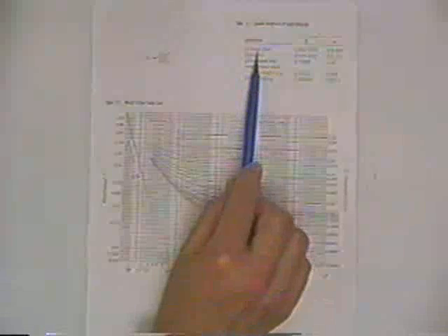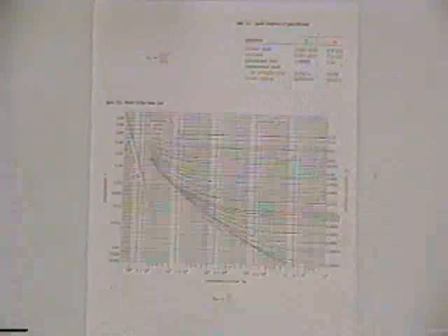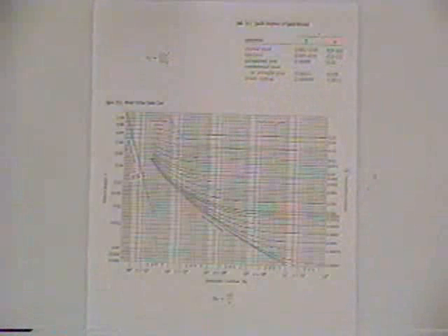And of course, the rougher the pipe, the more head loss you would anticipate. And so in your reference manual, you'll find a very brief table, and other references have very extensive tables that for different types of pipe give you the roughnesses in either meters or in feet. Now if you've got a rough pipe, but it's a big pipe with a large diameter, it's going to have a different effect on the flow than the same pipe material, the same amount of roughness represented by the epsilon, but a smaller diameter.